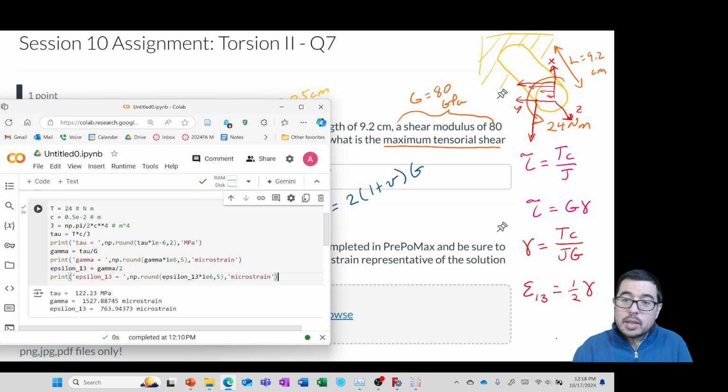Likewise, when we do finite element analysis, we are discretizing a perfectly round object with elements. So it's also somewhat unreasonable to think that the finite element analysis will be absolutely accurate, especially because even if we get that geometry perfectly ideal, it doesn't capture the non-ideal, realistic nature of the problems that we're studying.